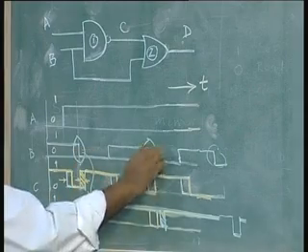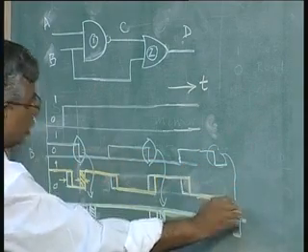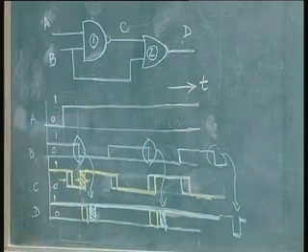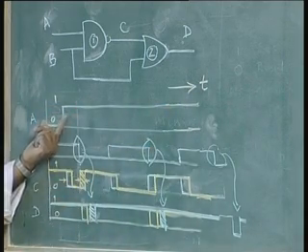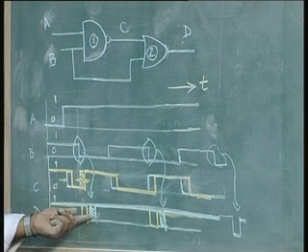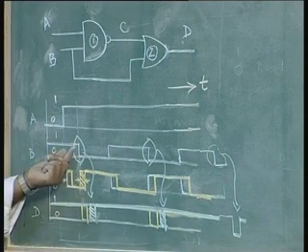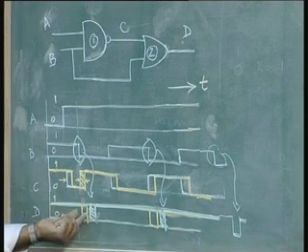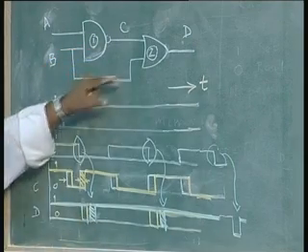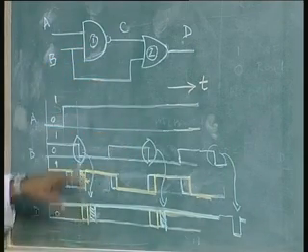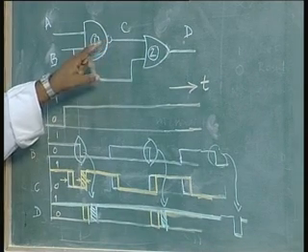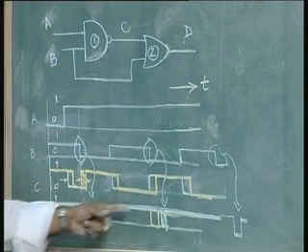Correspondingly there is an output pulse based on this input. I want a D input. So, clock is high, even though the clock is high, the D does not remain 1 all the time. Of course, D is 0 in this case, I will have to do some inversion. One of these gates has been inverted, this is only a concept. So, I have to invert one of these gates, maybe this NAND gate can be an AND gate. If you make one of these inversions, this becomes a positive pulse instead of a negative pulse.